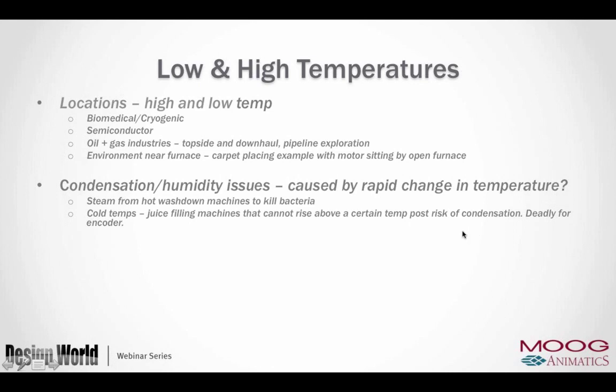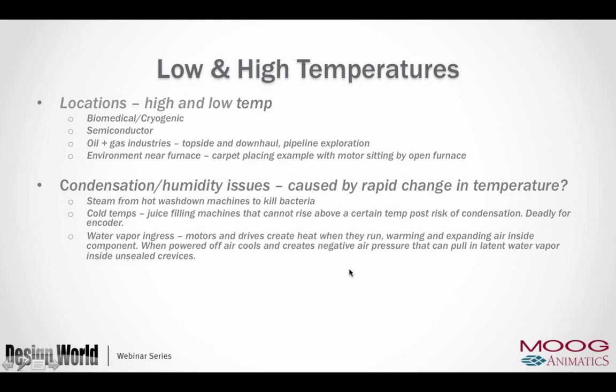condensation, that can be deadly for an optical encoder, because if it condenses on the read head, you can't read it. Okay? Water vapor ingress. Motors and drives create heat when they run, warming and expanding the air inside. When they're powered off, the air cools, creates negative air pressure that can pull that latent water vapor inside unsealed crevices. Okay? Always be aware of that.